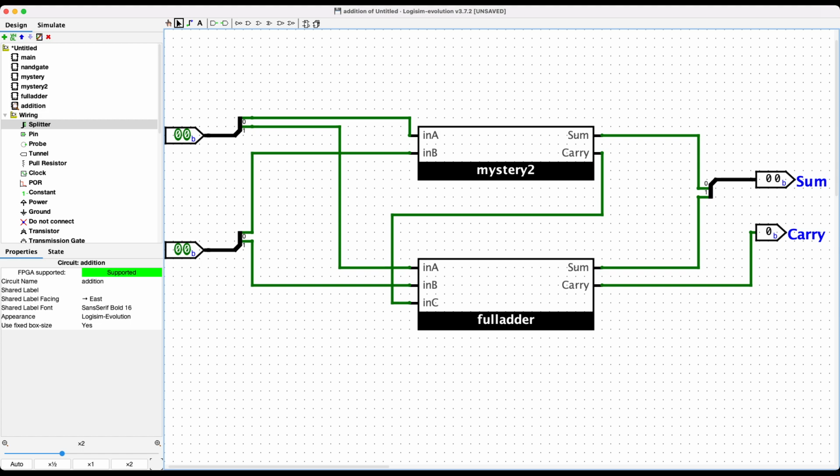All right, well, if we can build addition units, how could we build subtraction units? Kind of similar idea. Well, if I can do subtraction and addition, could I do bit shifting and bit rotation and logical operations? If we were to zoom out one more layer, what we would be building is called an ALU, Arithmetic and Logic Unit. It would have within it the addition component, a subtraction component, a logical OR component, a logical AND component, a bit shifting or rotating component, right? So it would have all of these different pieces inside of it.